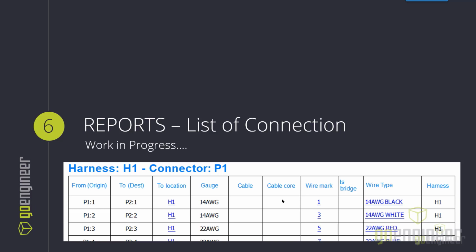But this is kind of again another modification that can be done to bring the wireless stuff. And this would be a good option as opposed to doing the connection labels on the schematic itself, which you have to manually create in current versions of electrical. Whereas a report is an automated way. You wouldn't have to worry about that being a manual, create a new symbol every time I buy a new connector.